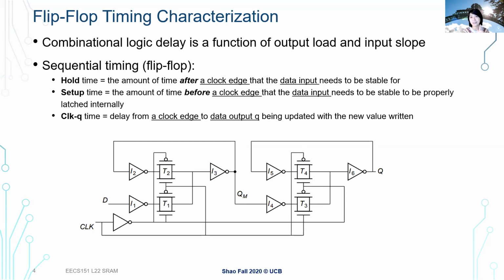There's also another constraint, again between the input and clock, which is the setup constraint, which happens before the rising edge of the clock. This is to make sure that our input is stable before the rising edge of the clock so that the data can be properly latched in the rising edge transition. So that's the setup and hold time pair. One happens before, which is setup. We need to set up the signal before the clock transition.